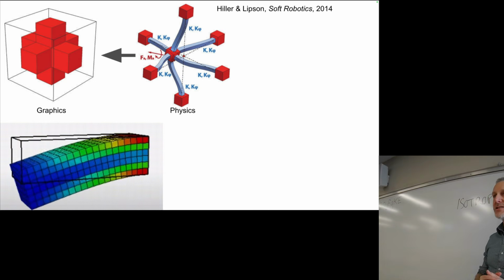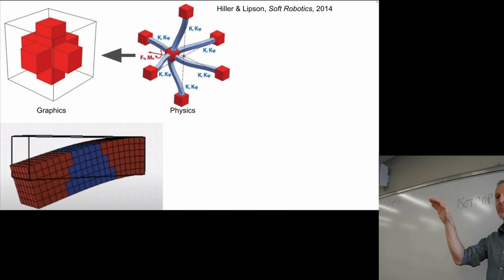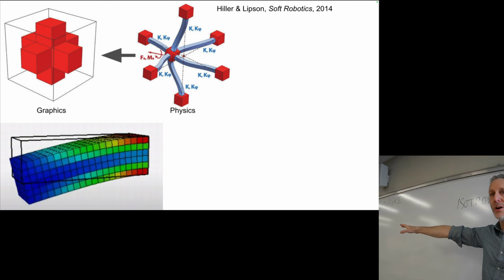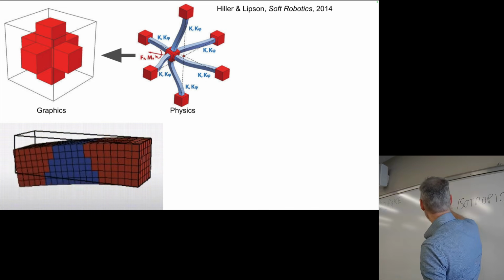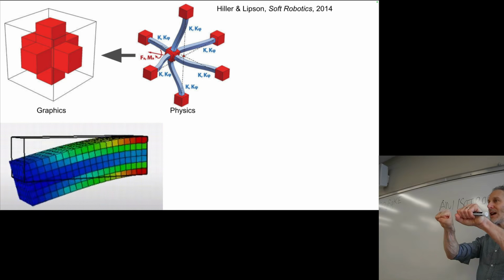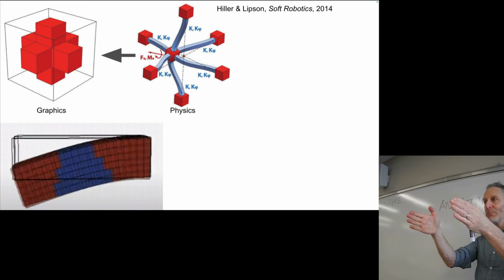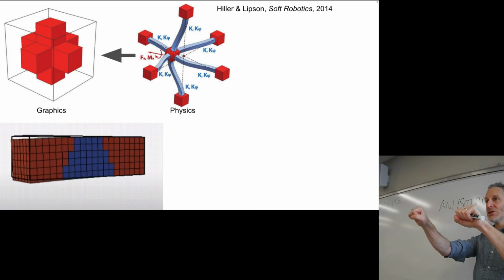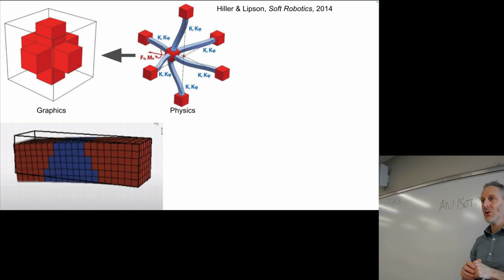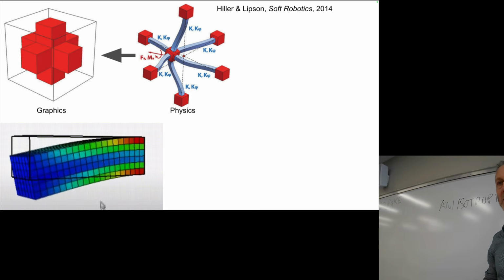So steel is an isotropic behavior. All of the K values are very similar, and they're similarly high. A big tranche of rubber, same thing. Anisotropic behaviors have very different K values. So for example, you might have a material that resists being stretched or compressed, but shear, which is these 2, it allows those quite a bit. It's quite permissive of those. There are materials in nature that have these properties. That's what we're doing when we change the K values.